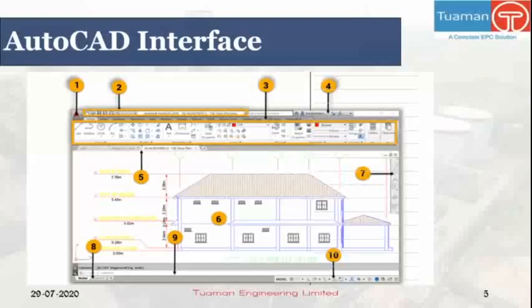It is the main medium of communication between the user and the AutoCAD. Besides the commands available from the ribbon, this is where we execute and provide dynamic inputs. Last is Status Bar. It is located at the bottom. It provides names, family, types, tips, or hints on selected elements.